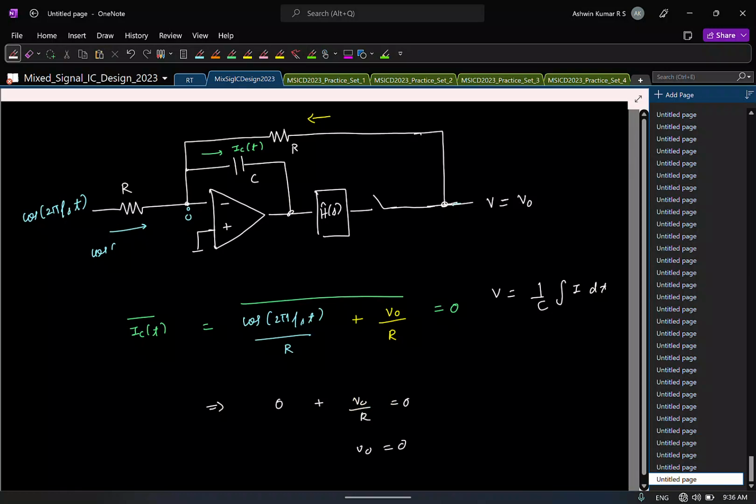So that is the nice thing about this continuous time implementation, which is two things. One, since the input impedance is purely resistive, the previous stage can easily drive this, unlike a switch capacitor stage. Second, because you are pushing the sampler after a filter, this filter itself will provide some inherent anti-aliasing. And loosely speaking, any error that you add here, remember this is the same place where quantization is also added,